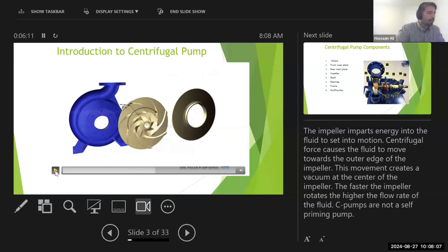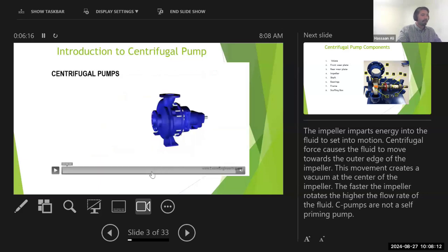One of the things that I want to mention over here is that at the discharge of the centrifugal pump, as it shows in the video, the pressure increases. The reason for that is the Bernoulli principle, because as the area of your casing increases over here, your velocity will decrease. And when your velocity will decrease, if people can remember the Bernoulli principle, pressure is inversely proportional to the velocity. So if your velocity is decreasing, your pressure will increase. So your static pressure on the discharge head will increase. And that is what you want as well.